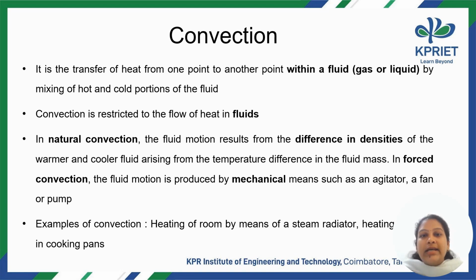Now let us look into convection. So convection is another mode of heat transfer where heat is transferred from one point of a fluid to another point of a fluid. So when I say fluid, I can imagine either a gas or a liquid. Okay, so convection naturally happens because of density difference. The best example that we can take is heating of water or boiling of water.